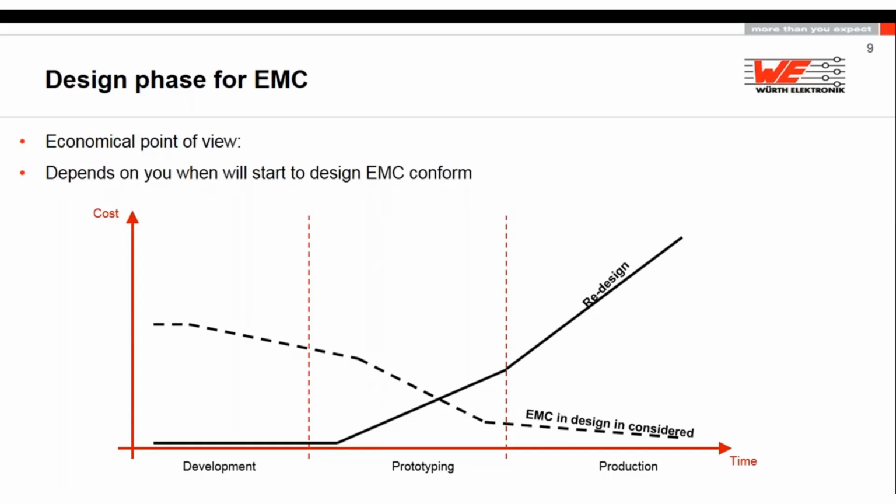When you know that you have a very fast rise time on some signal, or high currents, or you know the switching frequency of your DC-DC converter, you should take care about what happens with the harmonics and which kind of filter you have to design for this switching device. Sometimes problems in EMC happen because you're just not thinking about the harmonics, or not thinking that you will need a filter anyhow, or you want to save money on the filter and then you put a very expensive solution outside of the box with some snap-on ferrites, or you have to modify your complete shielding.